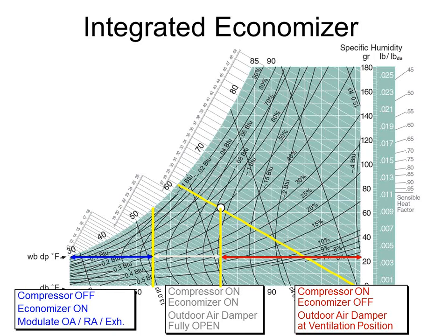If the thermostat in the space still does not get satisfied and the temperature continues to rise inside the space, then the second stage of the thermostat calls. And that second stage wires to the economizer controller also. The economizer says, great, and he ramps his damper open. Well, I'm already giving as much free cooling as I can. If it's not good enough, then I'm going to go ahead and allow the compressor first stage to turn on. All right.